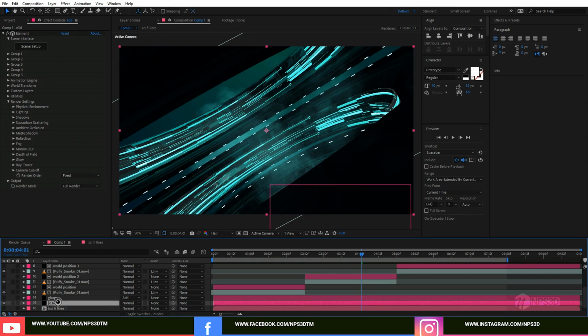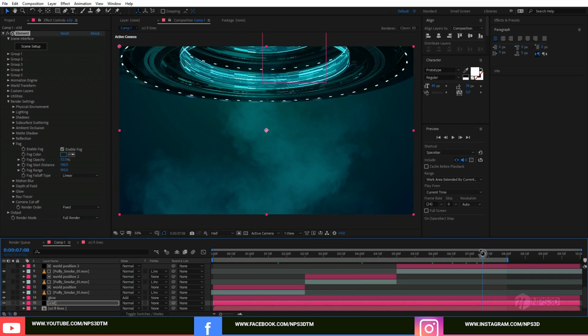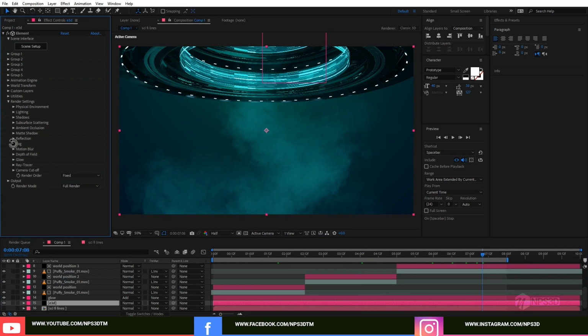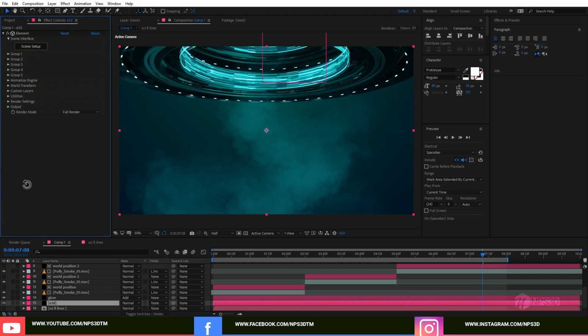Go to the Animating layer and go to the fog and enable the fog and choose the color, this one, right, and make it harder. Go to the main Element3D, and go to the output and enhance multi-sampling and super sampling 2, or just make it 4, and sampling and aliasing make it 2. So let's just save it, right?